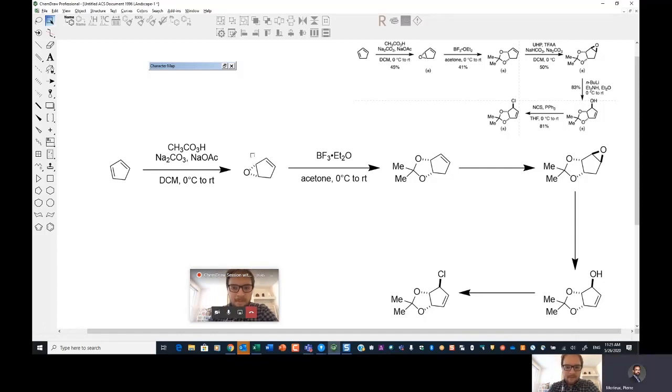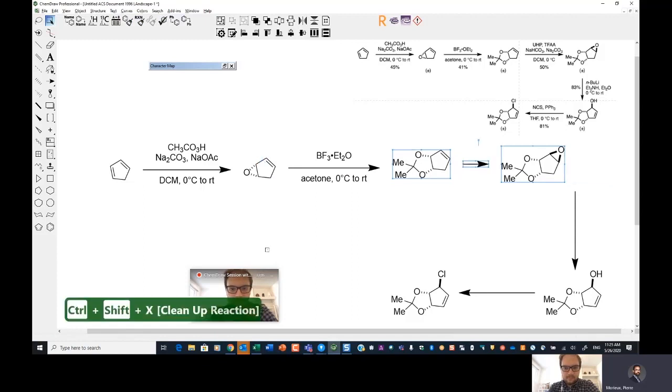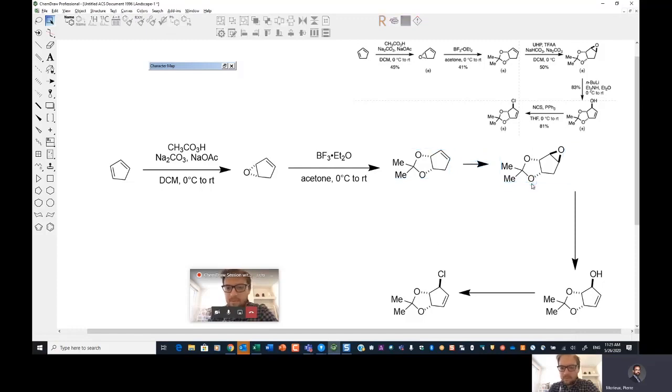Yeah. So really, the one thing is double-clicking on arrow to select entire reaction, and then cleaning that up with this button here, or Control-Shift-X or Command-Shift-X for cleaning up reaction. Cool. There will be some improvements in the upcoming version to better handle reactions that are not going left to right, because that's a little bug we have, but it's coming up in next.